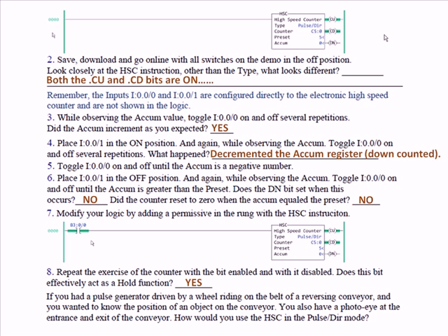Simple. Anytime the conveyor is moving, you either energize the forward motor starter or the reverse motor starter. So you know when it's going forward or reverse, you simply reverse the direction on the high-speed counter. Once the object passes the photo eye at the entrance of the conveyor, since you know the pulse rate of the wheel riding on the conveyor, and every pulse represents so many inches or so many feet, you can determine, once it breaks the beam on the photo eye, how far it is on the conveyor within the units of the length of distance for one pulse.